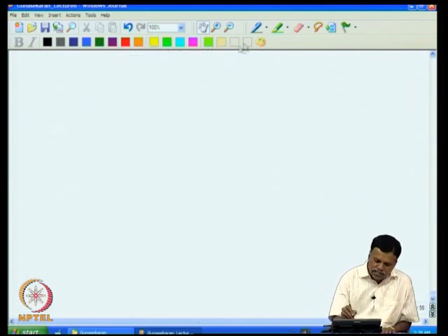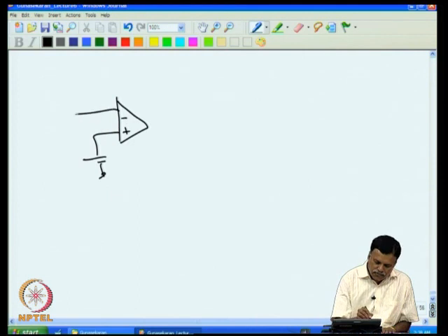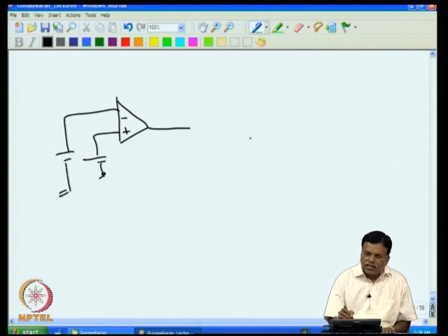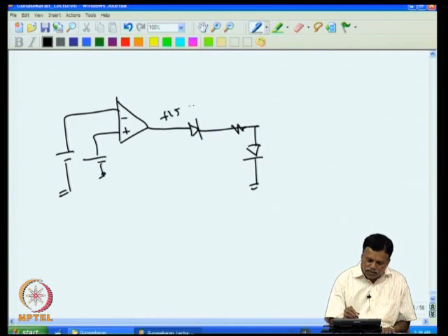So in case of thyristor, what we can do is we can have a drive, and then we have to fire the thyristor. Now thyristor has to be isolated. The easiest way of doing this would be to use an opto isolator. For example, whenever this is plus 15, then the diode allows this plus 15 to come. So you will have 14.4, and then the optocoupler needs around 2 volt.